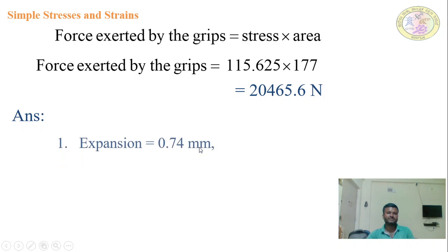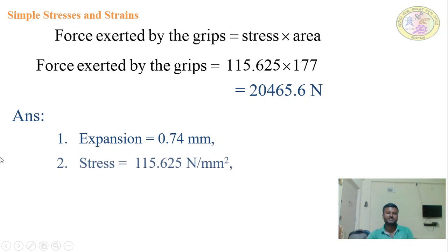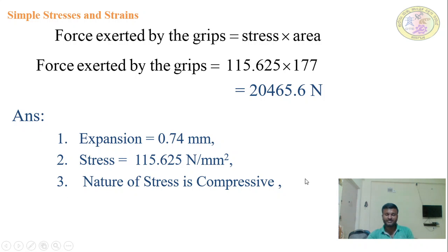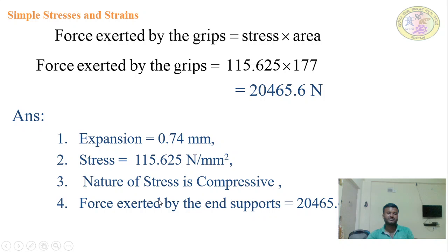Now the answer: expansion is 0.74 mm. Stress is 115.625 Newton per mm square. And next, the nature of stress is compressive in nature, and the force exerted is 20465.6 newtons.